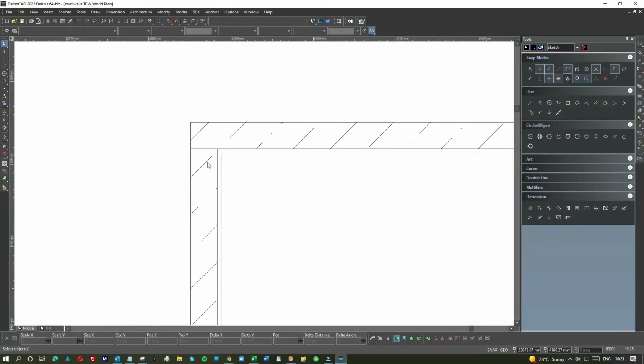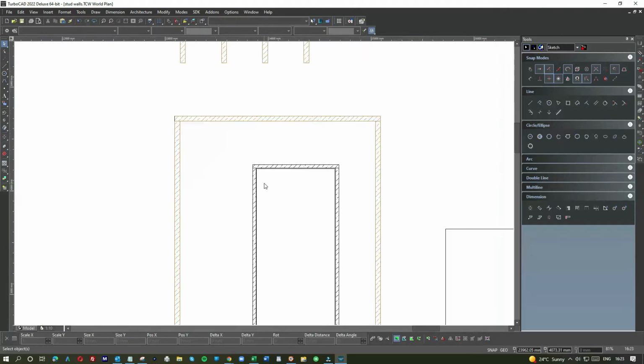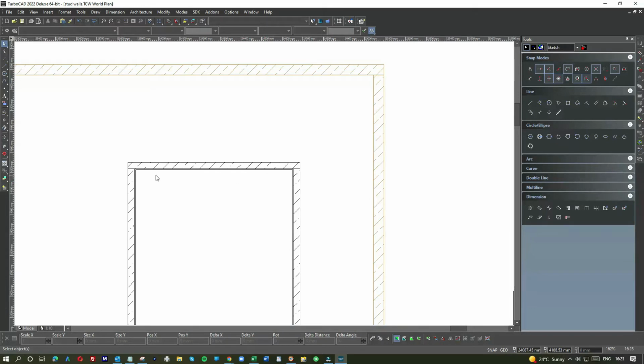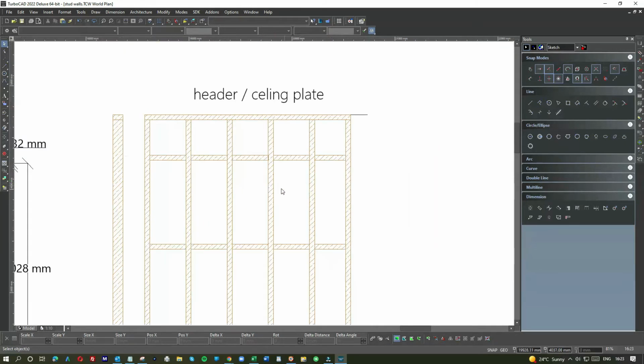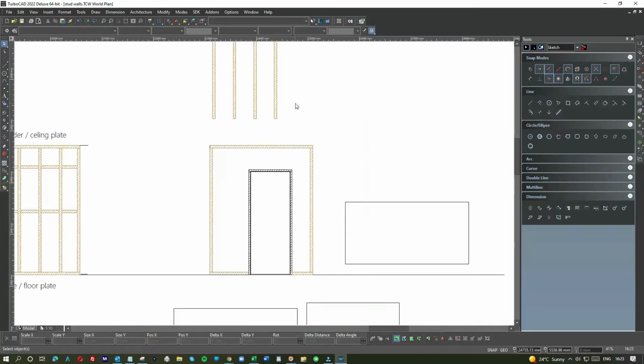Normally you put the studs in, but when you're making the allowance for the studs, you measure for the door, the 5 mil on either side of the door, and then the 32 mil lining and 32 mil lining. So what you don't want to do is create an opening in the stud work, say here for example, that's the size of the door. It has to be the size of the door plus the lining plus the margins for reasonable operation.